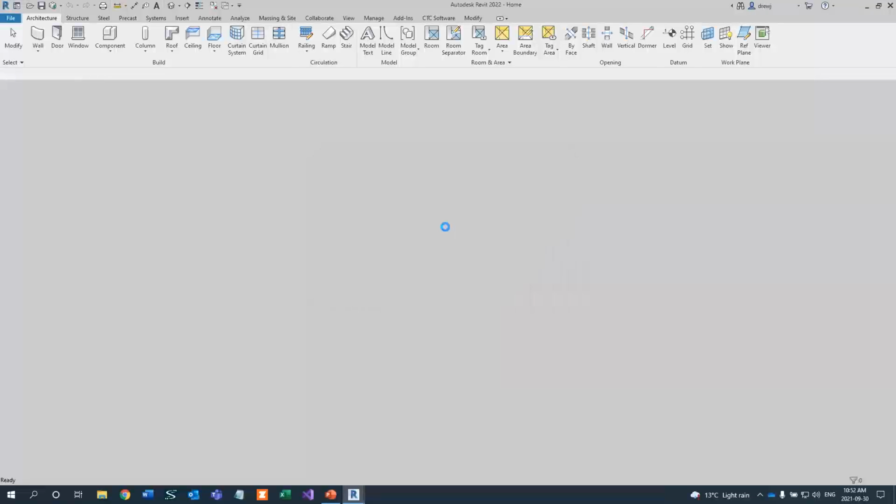This is how you would normally do it. Open it up with Detach from Central, preserve the worksets, and then you can do a save as your project file. That's why it all went wrong for me. So I could do that again. Okay. It's almost open. I'll have a little swig of coffee while it opens.